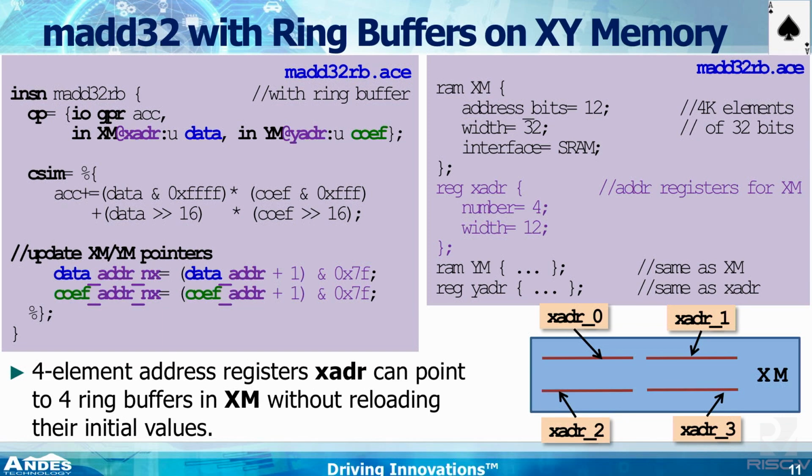We used to have a customer who wanted to do everything on the general purpose register, so you can count how many read/write ports you need. In this case, just I/O, you need 1 read, 1 write, and for the ring buffer address, also 1 read, 1 write. So you have 3 read, 3 write ports. So it's quite expensive. And they want 2 sets of this. So if you're able to define a special register for this purpose, that moves the pressure of register ports from the general purpose register to dedicated ports.